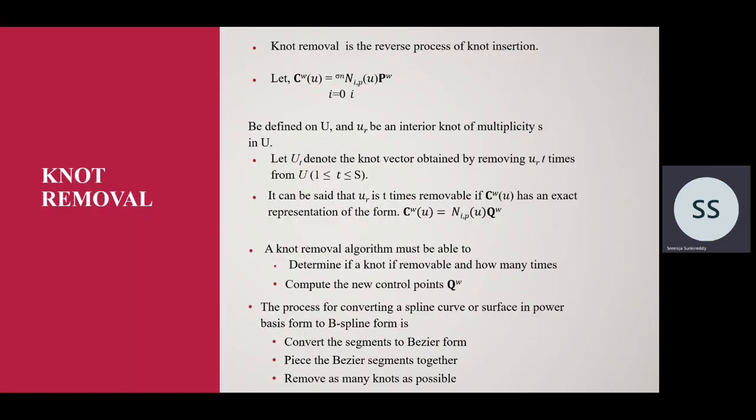And knot removal. Knot removal is the reverse process of knot insertion. By definition, it is the process of simplifying the representation of a curve or surface, and this is referred to as knot removal. This is done by removing some of the knots where curvature changes dramatically.